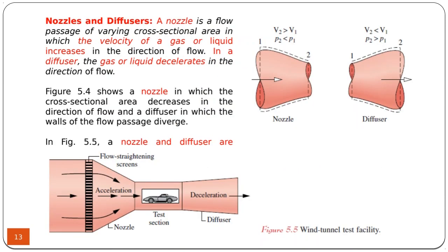So where can we utilize the energy equation for open systems in steady state? We have different applications of the energy equation for open systems. The most basic one is the nozzle or diffuser. What's a nozzle or diffuser? A nozzle is used to increase the speed of the stream overflow. So as the area is decreasing, just take a look at this.